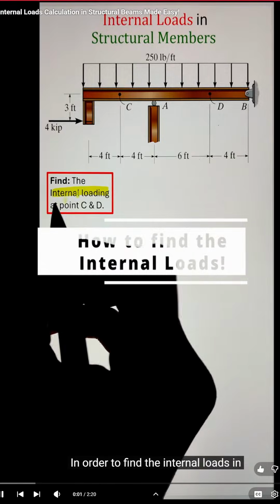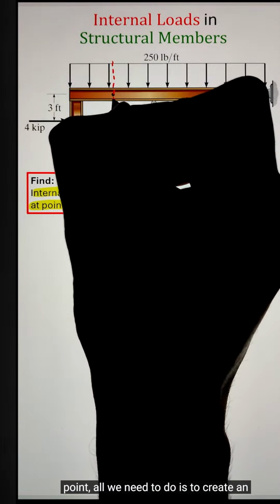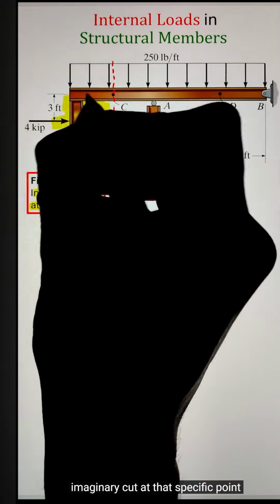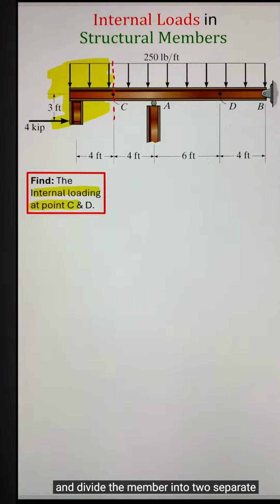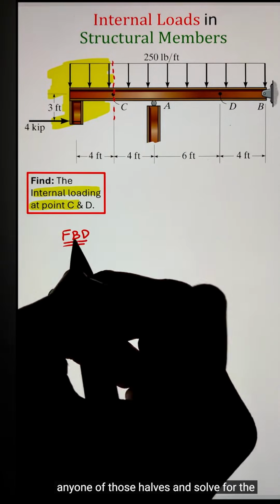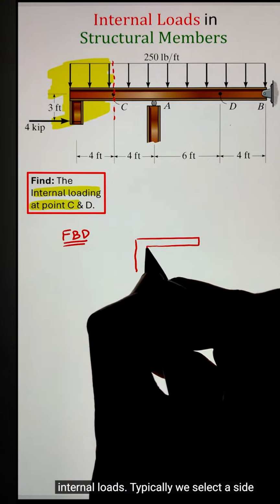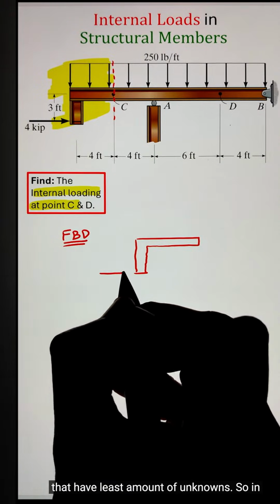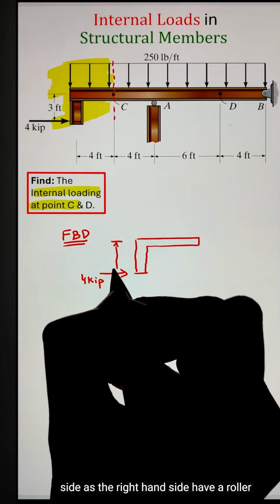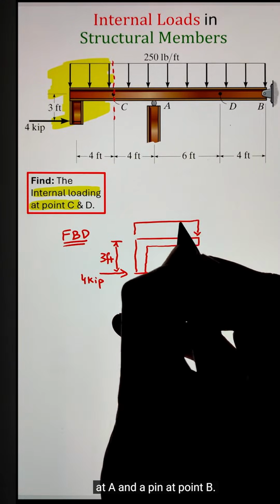In order to find the internal loads in the structural member at a specific point, all we need to do is to create an imaginary cut at that specific point and divide the member into 2 separate pieces. Now for analysis, we can pick any one of those halves and solve for the internal loads. Typically, we select a half that has the least amount of unknowns. So in this case, I'm going to pick the left hand side, as the right hand side has a roller at A and a pin at point B.